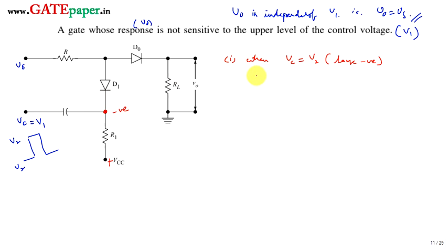So the voltage on n side of diode D1 is some positive voltage here plus some negative voltage, so you will get some negative voltage over here. Whenever Vc is at V2, a large negative voltage, even though it is plus VCC, the point over here is going to be a large negative value. That large negative value makes D1 forward bias.